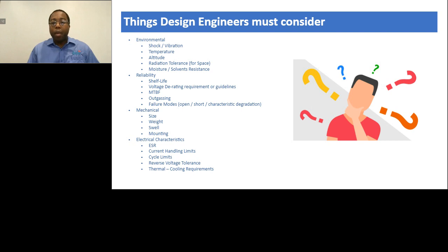SWaP savings requirements are becoming the norm. Finding a capacitor that meets specific size and weight requirements, in addition to providing robust and reliable mounting options, is key to designing within mechanical constraints. Some capacitor technologies can even swell over time, so designing in enough space around the capacitor to account for this must be considered.